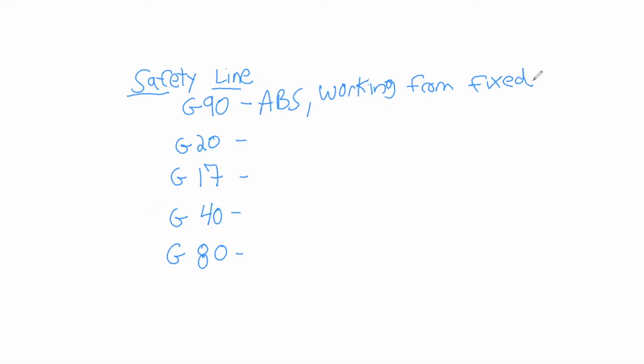G20 is going to verify that we're working in inches. If you wanted to work in metric or needed to work in metric, this would be G21 for metric.